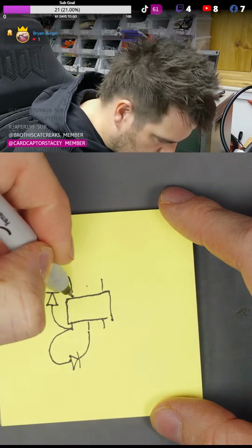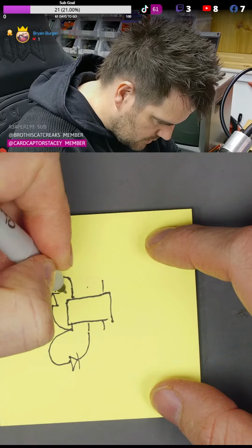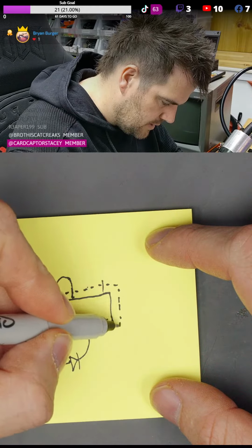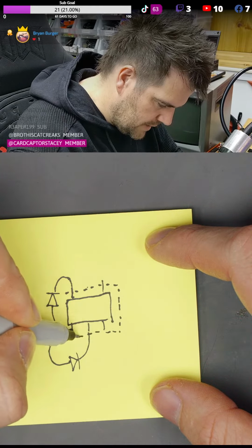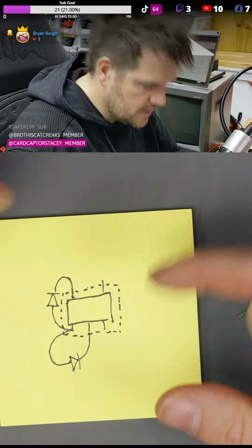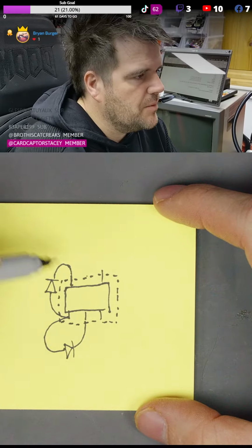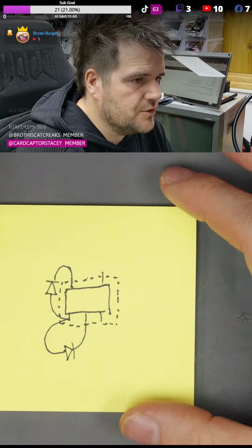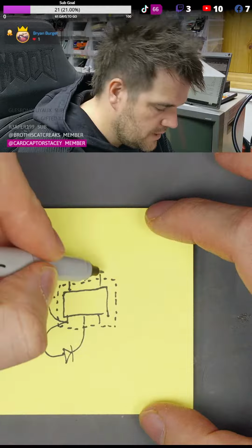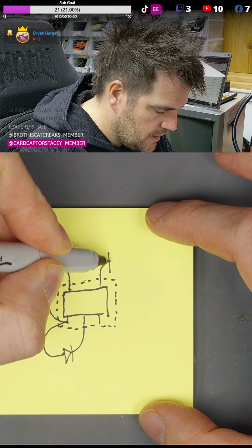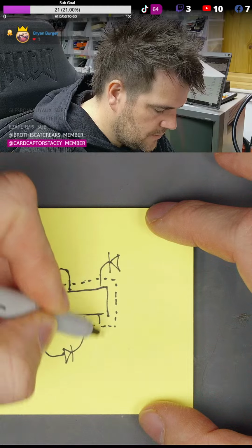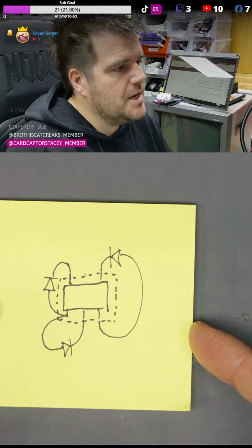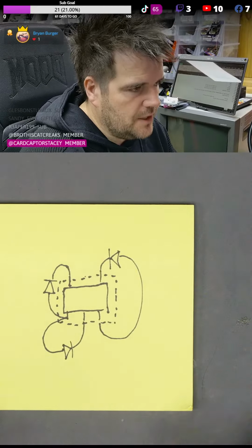And then obviously if I draw around where the pins are, I don't know whether this will make it less obvious or more. We'll try and highlight where the pins are versus the lines. Yeah, maybe a bit more clear there. So you've got a diode here, and this might be a transistor in a package, but measurement wise we're getting a diode. This was also a cathode there with an anode to here. So that's what I'm seeing on the measurements, just pure diode readings.